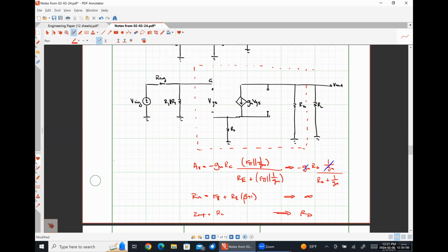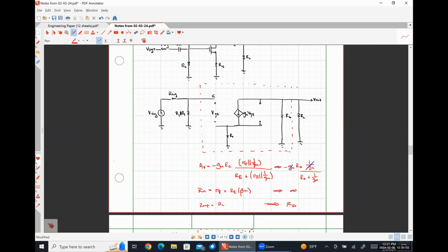These relationships in red are just for what is in the red box, right? So in the red box, the voltage gain, the ratio of the voltage at this node, if we were to call it V in, and the voltage at this node, if we were to call it V out, for a BJT with emitter degeneration, but also neglecting the early effect, would be this.